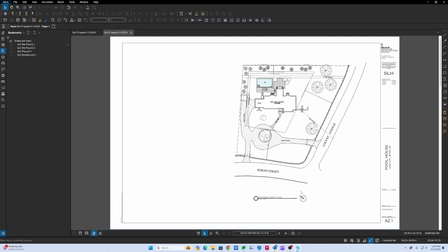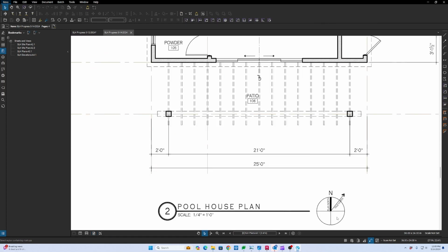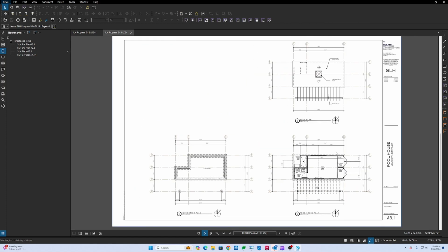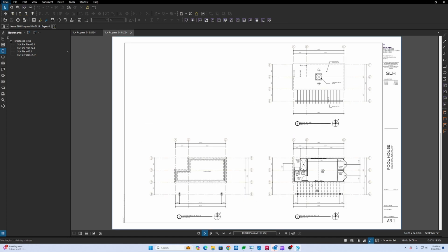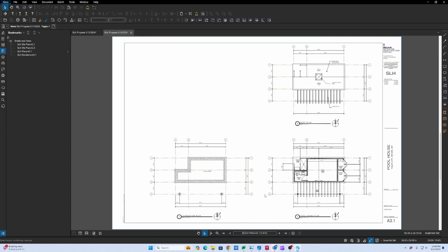Okay, so north is for existing, and proposed. Now, north is still up, obviously, because we rotated it. The actual north goes that way. But north is still up on the plan. So that's really a preferred way. Try to do north up when you can. And so that means our front with the trellis will be the south elevation, which we're calling out as the south elevation. So we just double check.